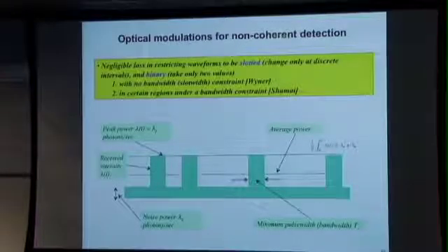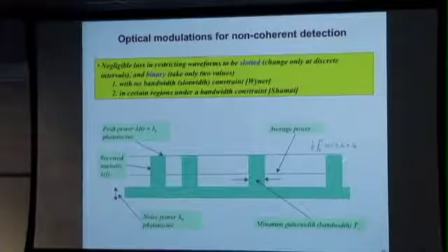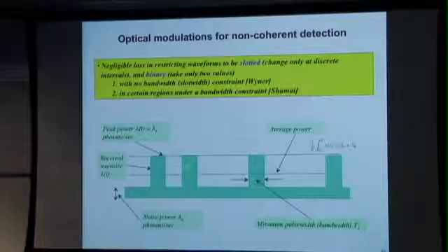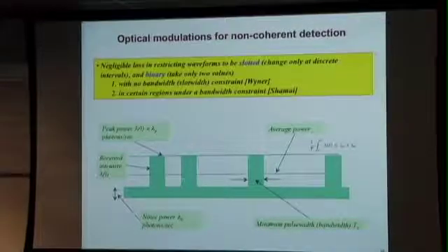If you want to use non-coherent detection, how do you design the signal? Basically, you just need to have some kind of waveform that communicates your information. And the real simplification is that the waveform doesn't have to be too complicated. If you just have a slotted type of waveform where you put a certain amount of energy in a slot or no energy in another slot, except with noise, you're going to probably detect something there anyway, but that is pretty close to being optimal. So just binary and slotted does the job pretty well.